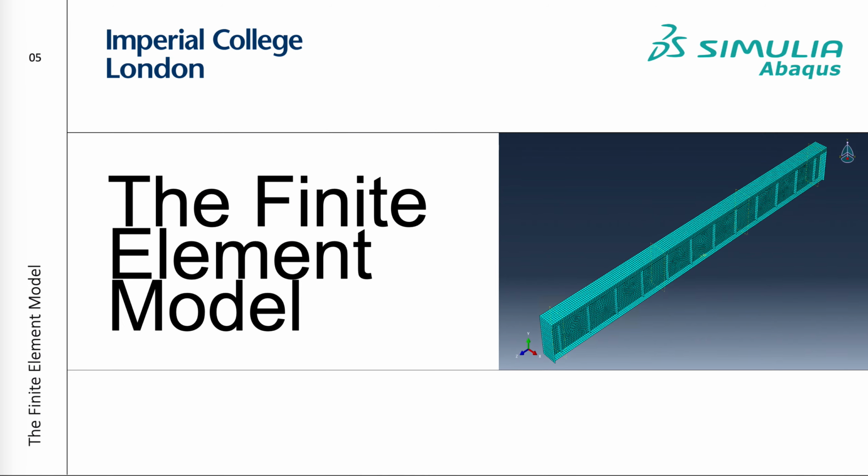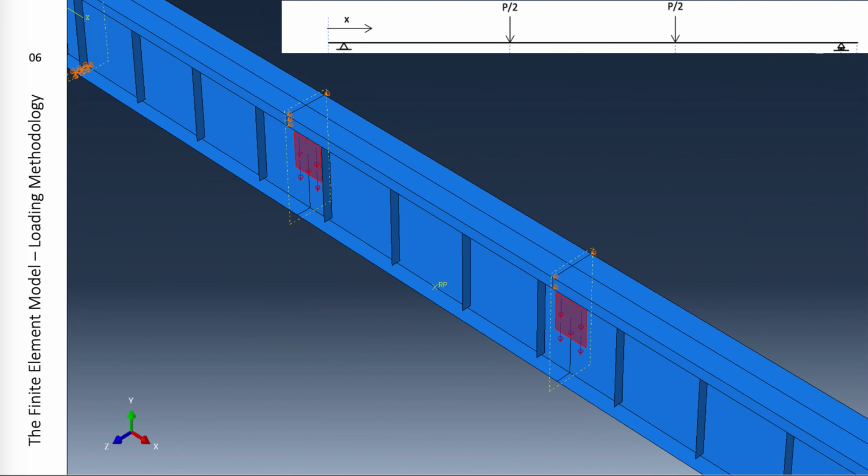The next stage involves carefully modeling in Abaqus in accordance with specifications. The loading is applied as uniform traction over load plates, which are small relative to the beam, so they are effectively point loads as assumed. This configuration meant shear punching failure due to concentrated and destabilizing loads can be neglected.